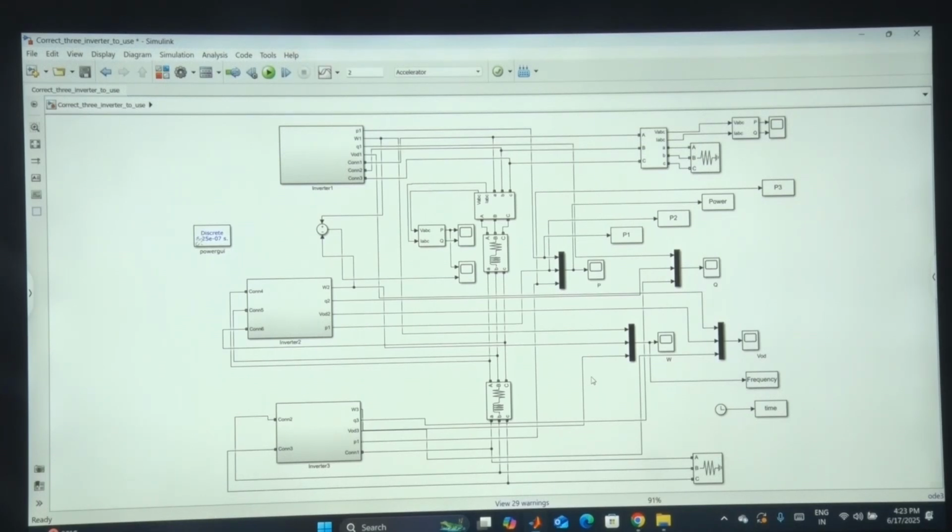Okay? Otherwise, what would it feel like? Let's say you have a sine wave. You are taking 10 samples. So first sample, second sample, third, fourth, fifth, sixth, seventh, eighth, ninth. The 10th sample should be perfectly aligned where the first sample was. Right? Or maybe if you are taking 10 per cycle, then the 11th one should be at the same location where the first one was. If that doesn't happen, if you don't align your samples properly, then what will happen? The next cycle, the first sample will not start at absolutely the same point 0.